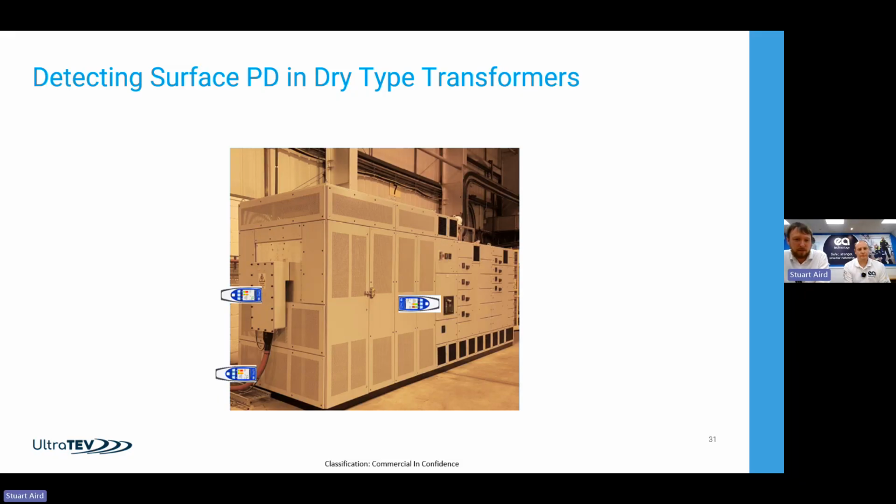There are air vents right round, but there's also a lot more open connections, a lot more dust, etc. collecting in there. Lots of other failure modes creep into these transformers that are more likely to give you surface activity that we can detect ultrasonically. So you're taking measurements in a lot more locations. From an ultrasonic point of view, you also have the challenge of the 50 hertz hum, the natural hum and load variations of a transformer. So that's something to be wary of.